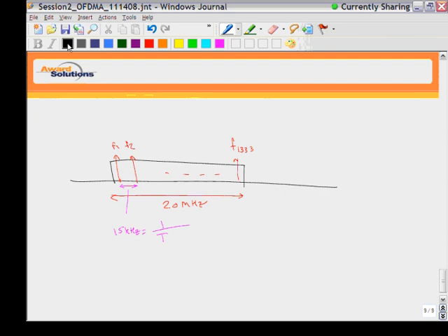But we said we can use only 1200. The question is why we use only 1200 out of 1333. The short answer is to meet the spectral mask requirement. The FCC has given us this 20 megahertz spectrum, so we cannot send our signal outside of that.